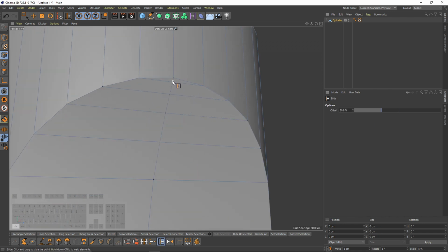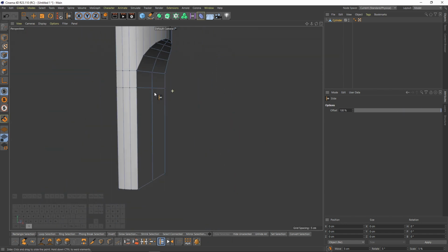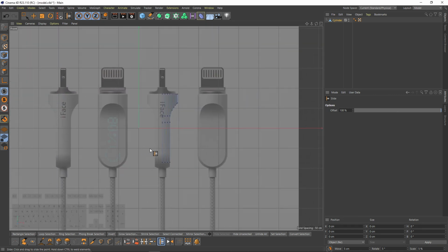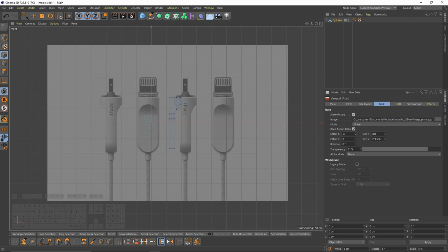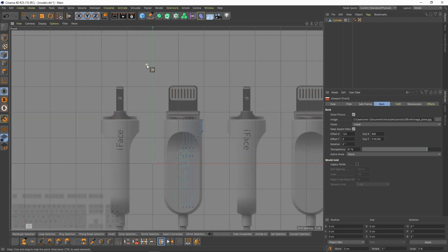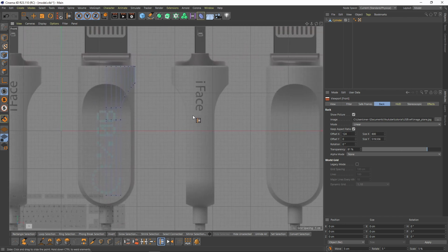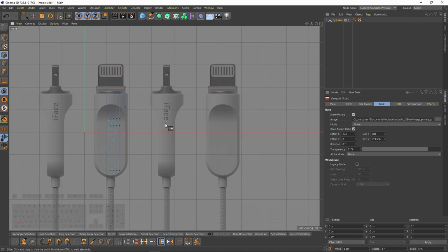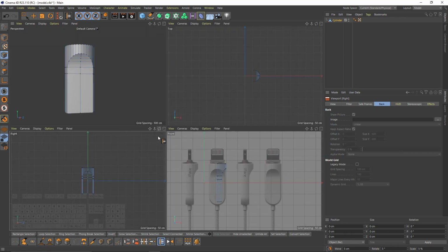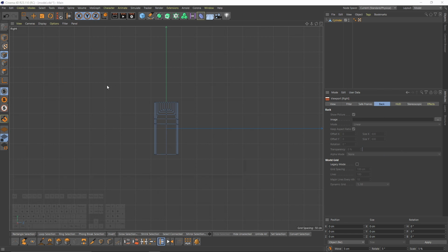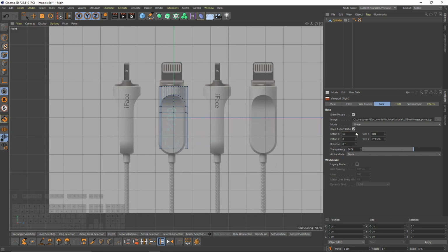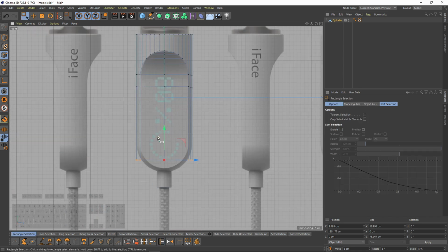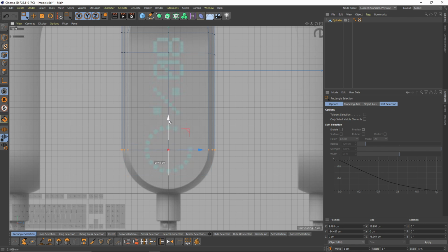And I can at that point select slide, press Ctrl and move it to the next point. Now let's try to make the bottom part. But first let's go to the front view, press Shift and V and change the offset. Like that. Actually no, sorry. Let's go to right view, press Shift and V and load the same image. And change the offset. Like that. Let's move these points where the curve starts.